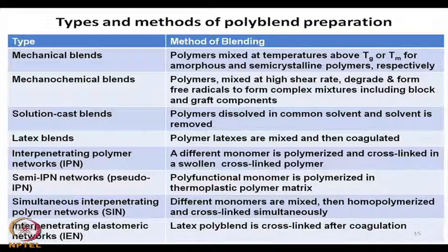After proper selection of the solvent, the component polymers are dissolved in a common solvent and mixed, and after mixing the solvent is removed by evaporation, and that can be recovered for reuse, and the product becomes a blend of two component polymers.